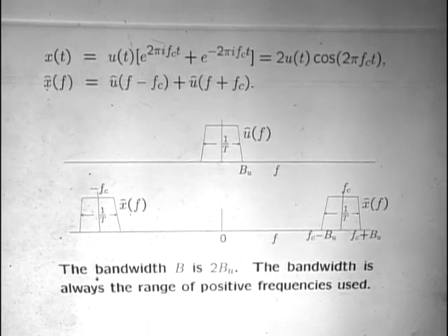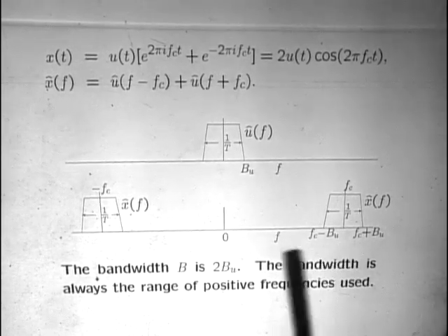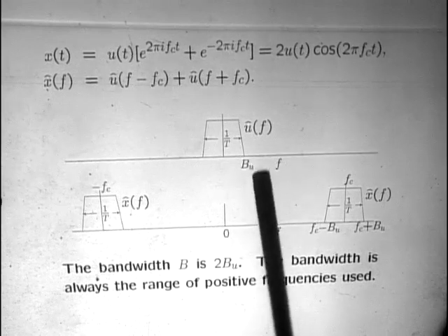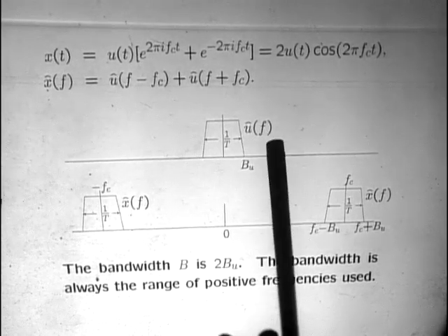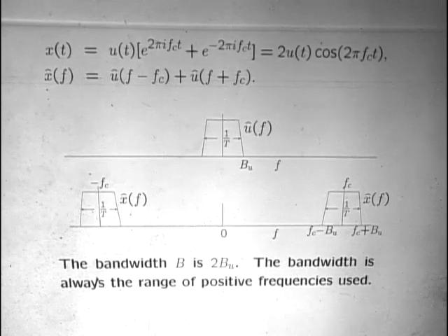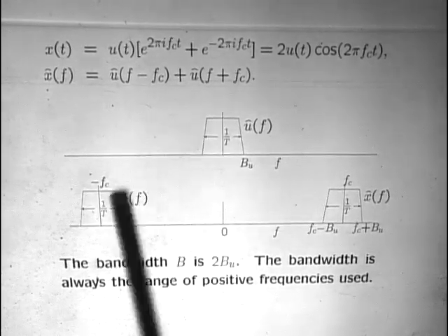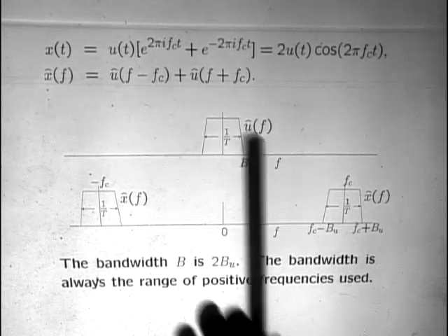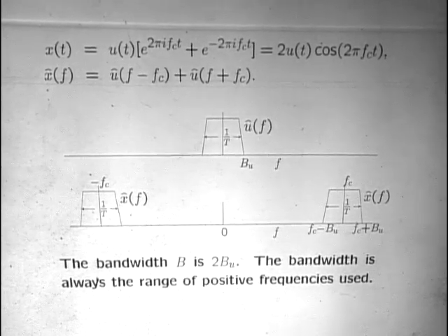And the transmitted waveform then exists in the band, which I'll call B sub u. B sub u is the bandwidth of u of t. Namely, it's this baseband bandwidth that we've been talking about. But unfortunately, when we do this, this thing is shifted up and this thing is shifted down. The overall bandwidth here is now twice as much as it was before.